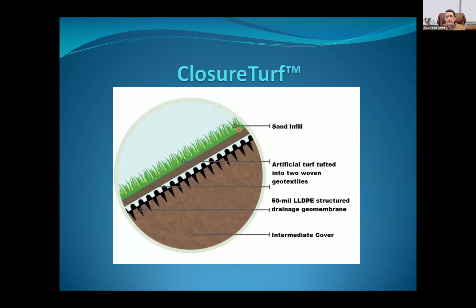They have made a few changes since then. There are other options. You can now use a 40 mil double LDPE. You can still use the 50 mil double LDPE. And instead of a sand fill that is used for ballast and drainage purposes, now they have a proprietary fill. That's good for locations that don't have a sand pit close by. For this case, at the Tangipahoa landfill, we used sand fill. We had good sand close by in a borrow area that met the specification, so we used the sand fill.